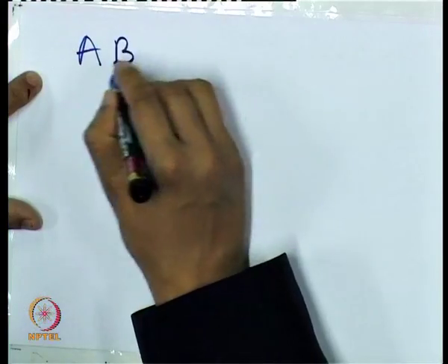But I would like to now, in addition to the Z and Y parameters that I described in the past few lectures, and the S parameters, as that is what we have been discussing extensively, mention another class of circuit parameters called cascade parameters or ABCD parameters, which are also quite useful while describing microwave circuits. So let us see what ABCD or cascade parameters are.